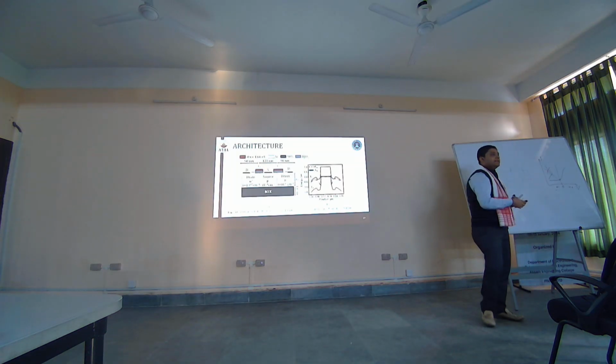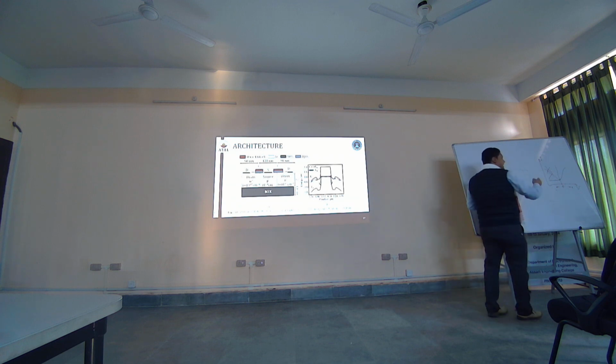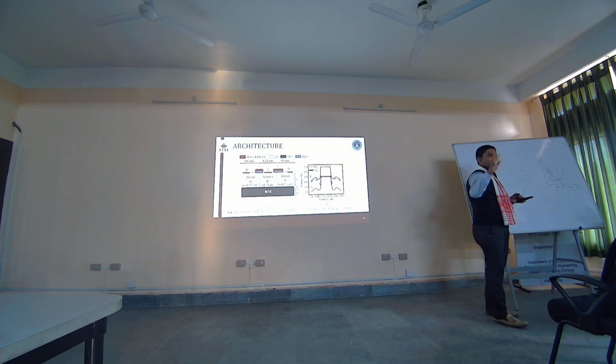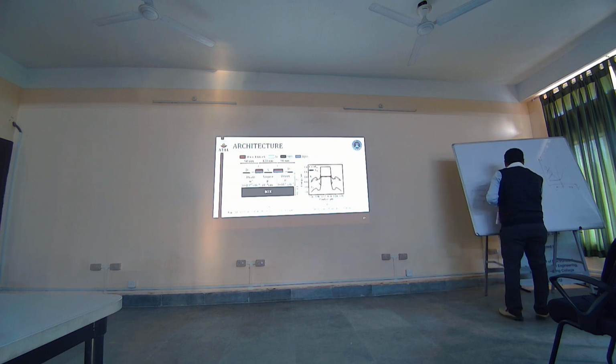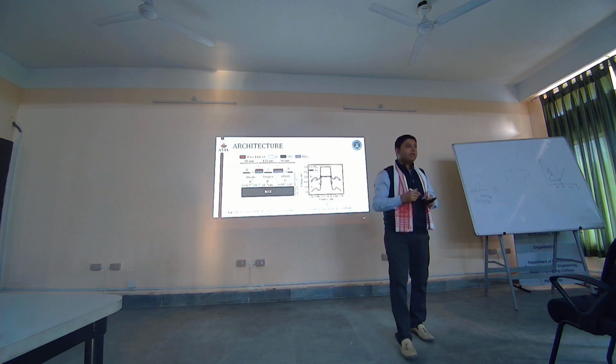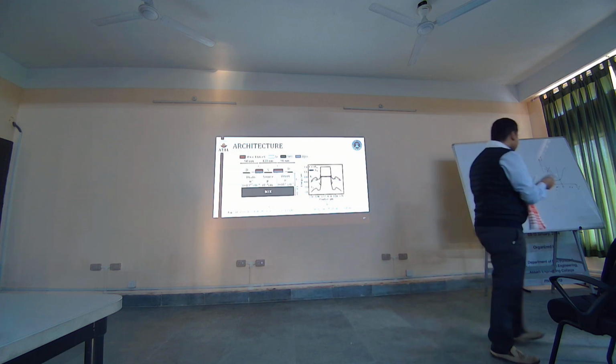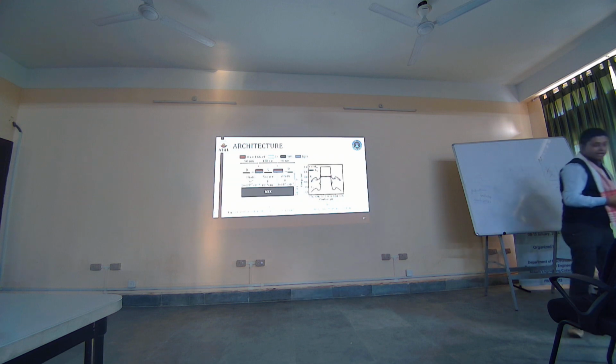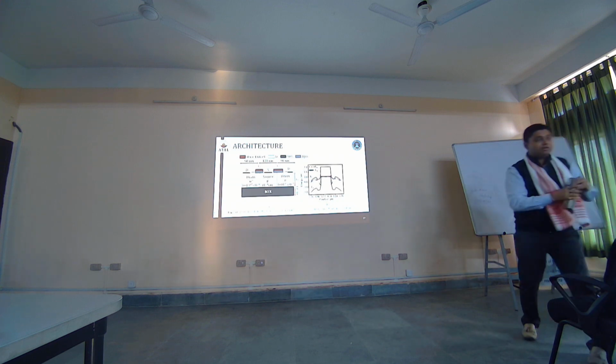They said that since I have to increase my current, the only way of increasing the current is to increase the number of gates on my device. Because when you have more gates, you have more bending, more depletion, and then quicker inversion. So they did this double gate MOSFETs. This is a very old technology, but people have been applying this for many emerging devices.